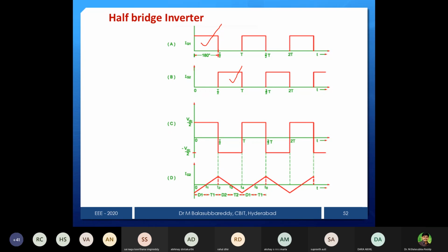That's why current will be decreasing. Again at this point, even though a pulse is available, if D2 is conducting, that reverse biases T2, and once D2 also turns off, then T2 will fire. Like that, I mention every instant. And again I will explain at the time of the inverter experiment.